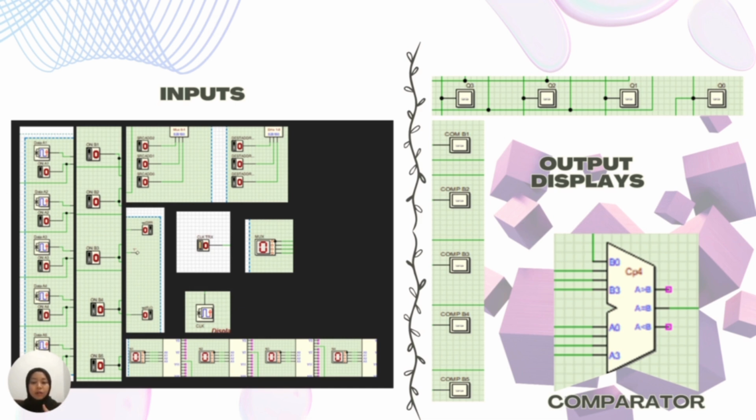For the count-out counter, the display shows the value 0 or 1 of each D flip-flop, tracking the counter progress in real time. For the comparator, it compares the 4-bit hex input with the count-out counter value and the stored password, outputting high if they match and low if they do not.